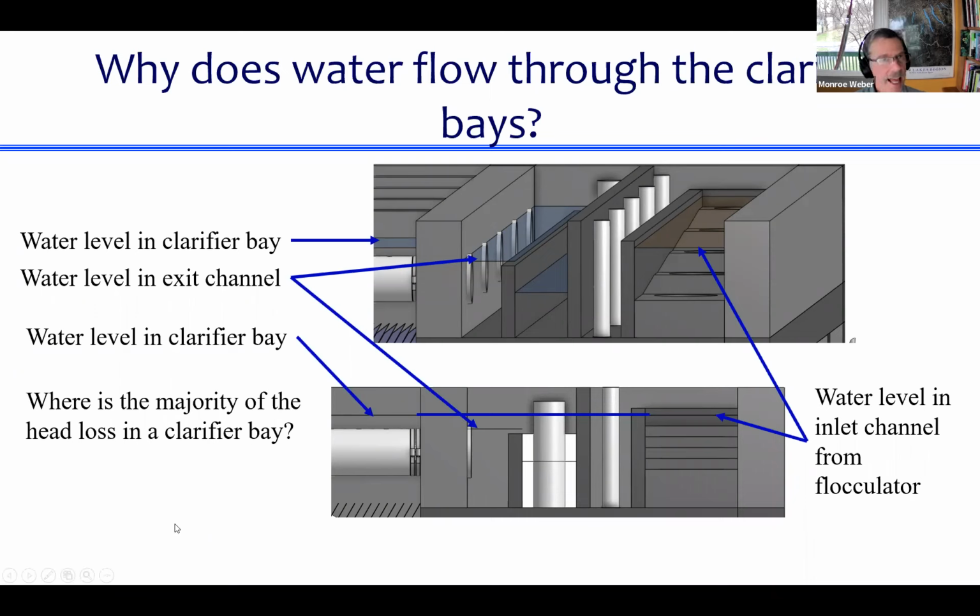And then that raises the question of, well, in general, we try to save energy going through the plant because all the elevation drops that we have force us to build a taller building. So it costs us money. So the question is, why is there 5 centimeters of head loss there? So you can hold that as a puzzle. Why didn't we just drill bigger orifices? We could have easily done that, right? It would be trivial to make the holes in the pipe bigger. So why did we intentionally make there be 5 centimeters of head loss there?